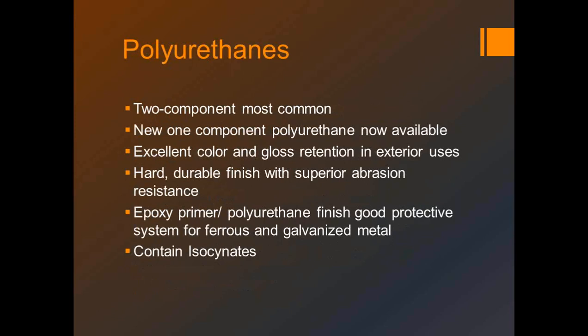There's just really not, but when it comes to steel, particularly, polyurethanes are one of the best that you can use. If you're looking at different levels, using epoxy primer and urethane finish coat, a couple coats of urethane on exterior environment, and you'll get a very, very durable system. The only thing next slide up from there is polysiloxanes, and we'll talk about that one in a minute.